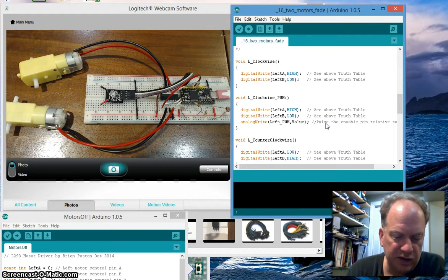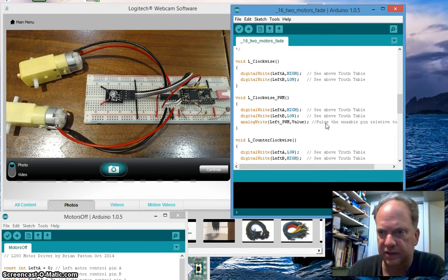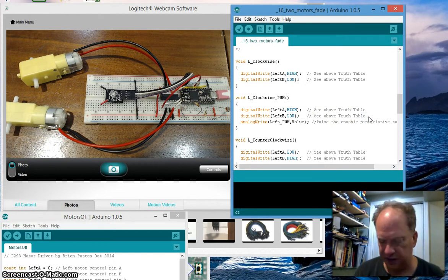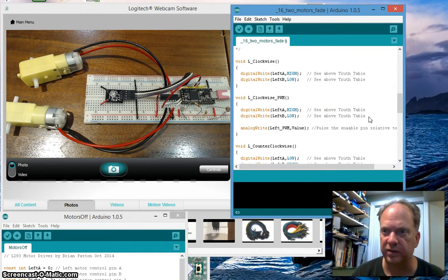But remember, the photoresistors were taking in values from about 30 all the way up to about 1,000. So we can only handle a number up to 255 here, so we need to scale it. And here comes the map. Let's do it quick and easy to start with. It is remarkably easy. Actually, I'm going to show you something else kind of cool. Because we're going to play with this, we're going to come back to it, we're going to test it, we're going to build on it.